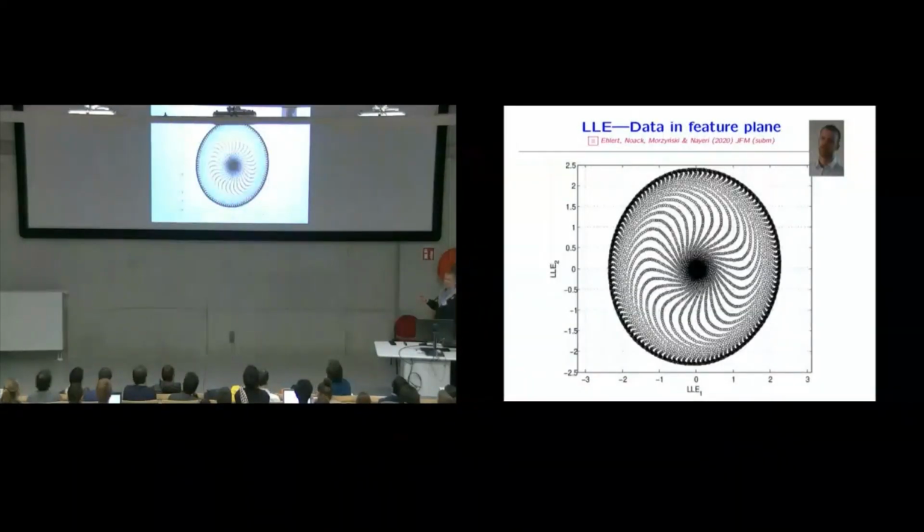I've shown these results already in my first lecture. So steady solution, limit cycle, and here you see the transients are going outwards. And you can go backwards from these feature vectors to the original flow, and you have something like a 1% of representation error maximum. Now, if you do this locally linear embedding, you assume already you have your flow structures, and you did CFD.